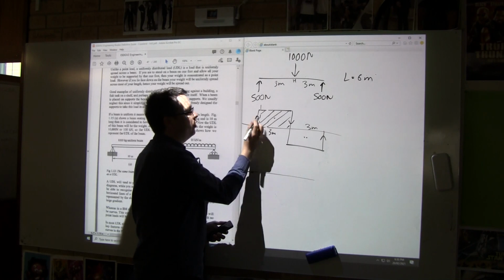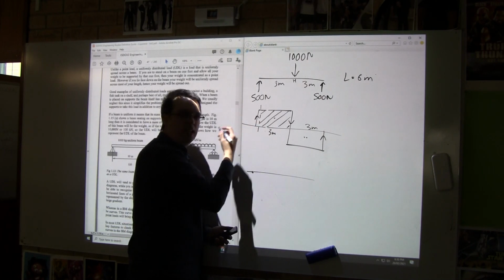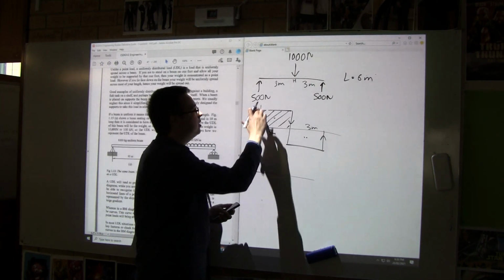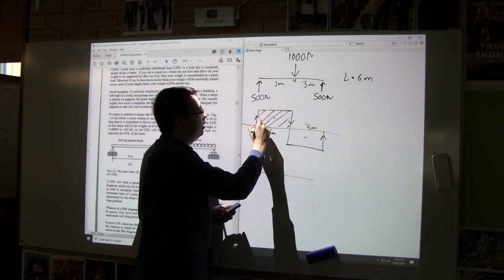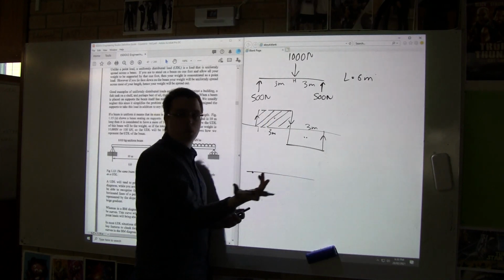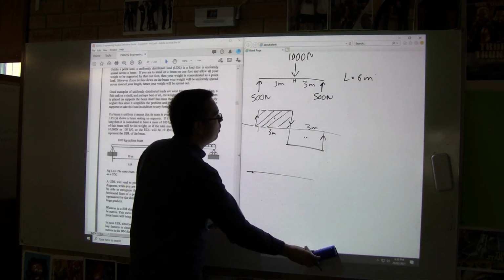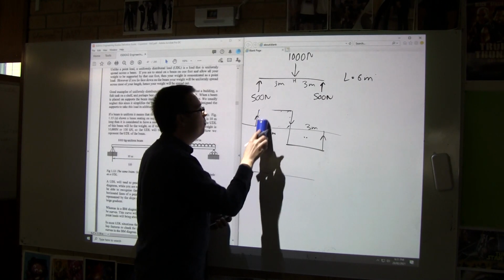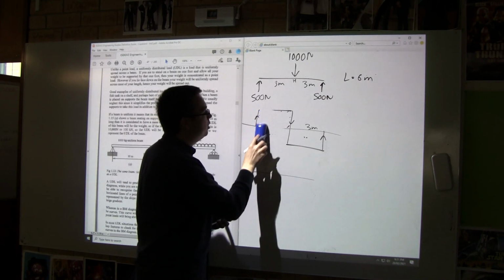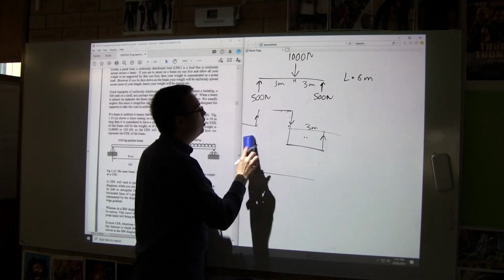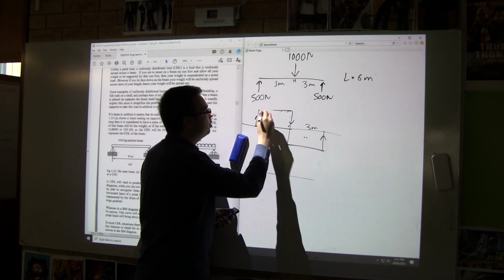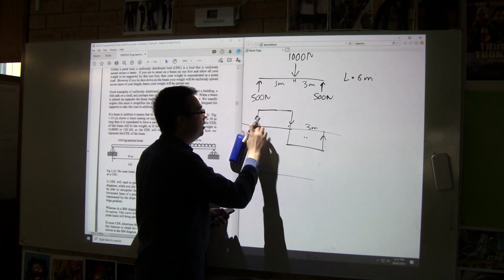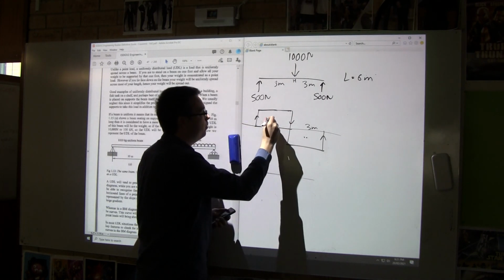Eventually getting to the point where if you go to 0 meters, that thing has to be 0 because there's no left-hand side of that. So what that means is that when we get all the way to here, this minus that is 0. That's how I approach it. We know it has to start and finish at 0 at the end of the beam. It doesn't have to be 0 at the reactions, it has to be 0 at the end of the beam, because we've learned already that there can be cantilever beams. We talked about how Copeland says he loves a good cantilever.